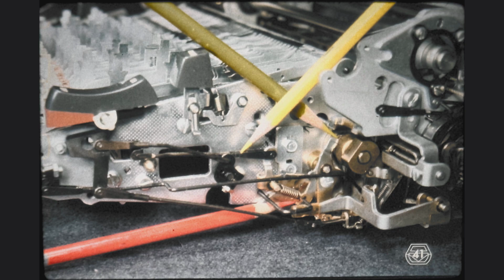In connection with the input to printing operations so far, we have covered the theory of operation of a total of 6 selector latches. We will now study the 7th latch, which has the ability to release the velocity control cam follower at the point indicated by the red pencil. Let us take this in small steps. We mentioned this mechanism earlier as an example of a mechanism driven by negative power or spring action. In its controls, this mechanism may look a lot different from the -5 rotate mechanism, but it works in exactly the same way.